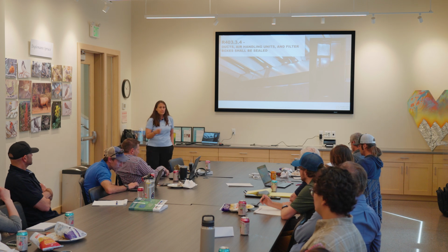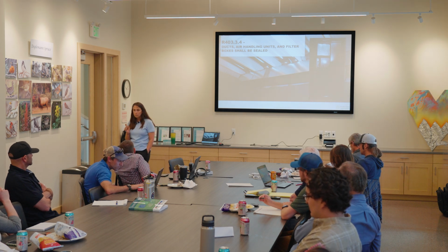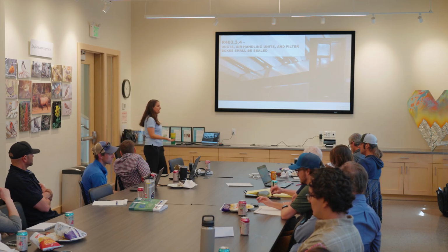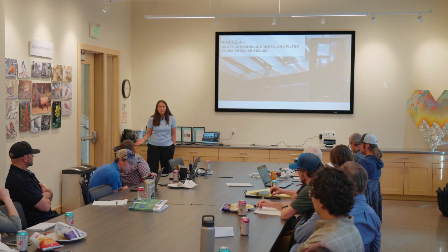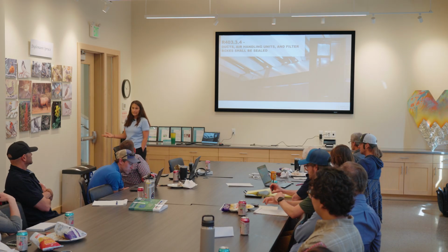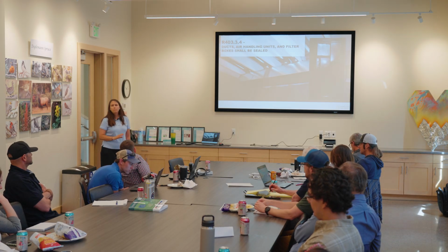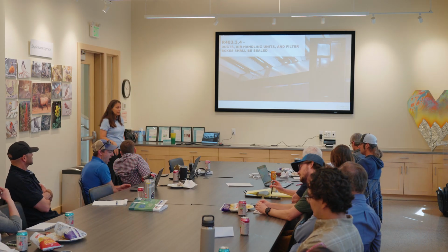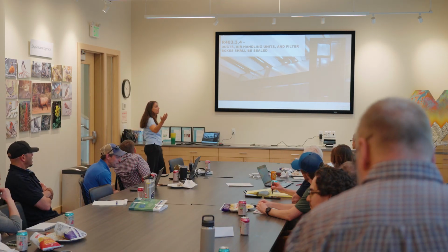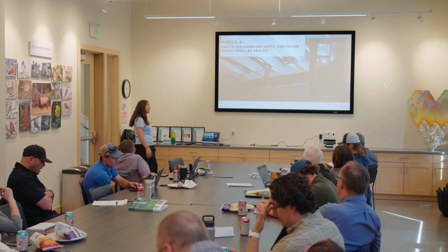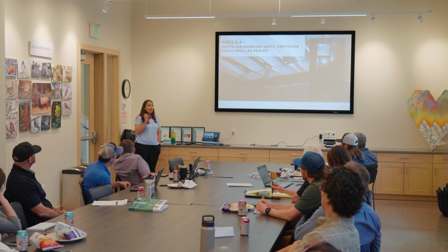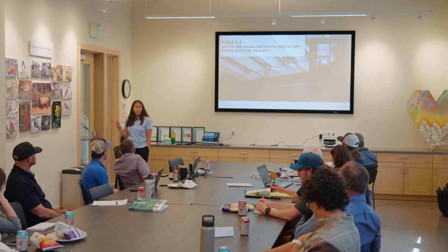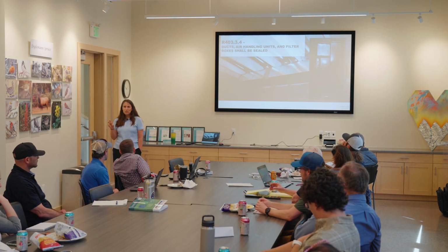So I want a note that says, hey, seal up ductwork. You know, we can say per the section and the IMC. Some people say per the IMC, or the mechanical code, and I would be okay with that too because this section also refers to sealing it how it needs to be sealed. SMACNA, that's another one. As long as it has something very visible on a non-hidden page,